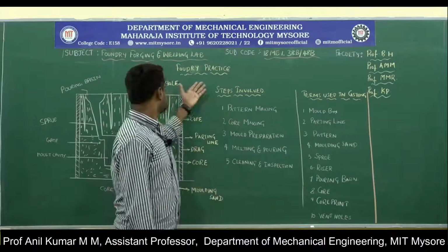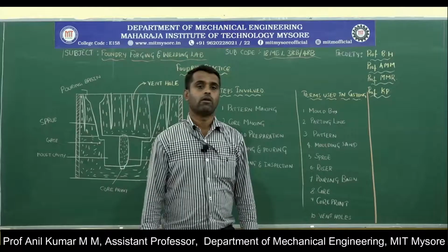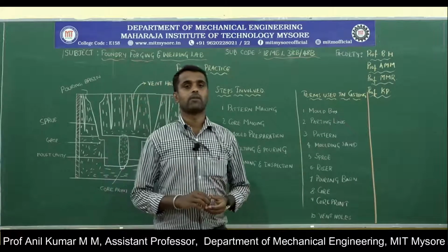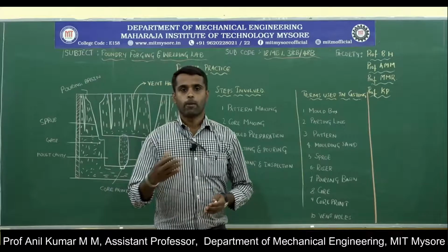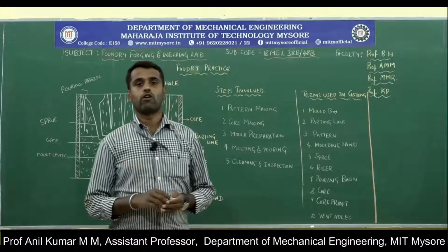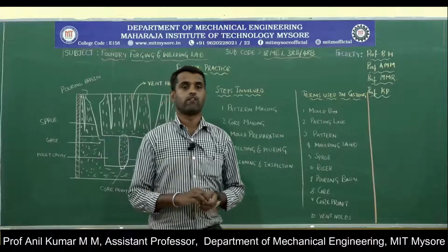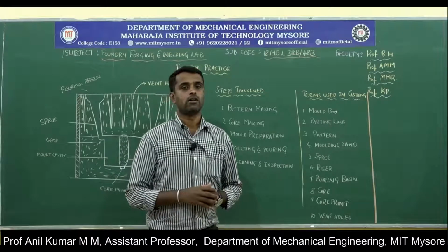Next, let us discuss what I mean by casting. Casting is one of the oldest types of manufacturing process in which metal is melted and then poured into the mold cavity and allowed to solidify. After solidification, we take out the solidified part and clean it, and that solidified part we call the casting.